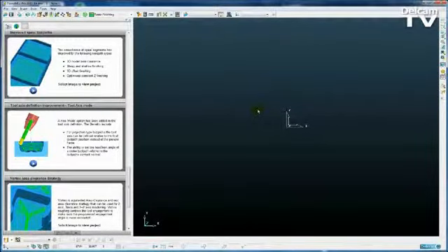There have been some significant improvements to tool axis definition for PowerMILL 2013. A new tool axis mode option has been added to the tool axis definition form. This gives big benefits, including the ability to set the lead and lean angle of a raster toolpath, for example, relative to the toolpath's contact normal. So this effectively gives us multi-surface, surface normal raster finishing.